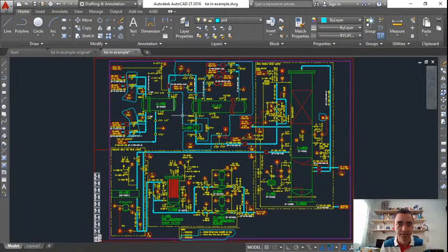in this case, to add this new equipment, I need to stop my process. I need to drain everything that I have in this system. I need to purge that to guarantee that I don't have any kind of flammables. And once I do that, the mechanical team will go here and will do the cuttings to the pipeline.